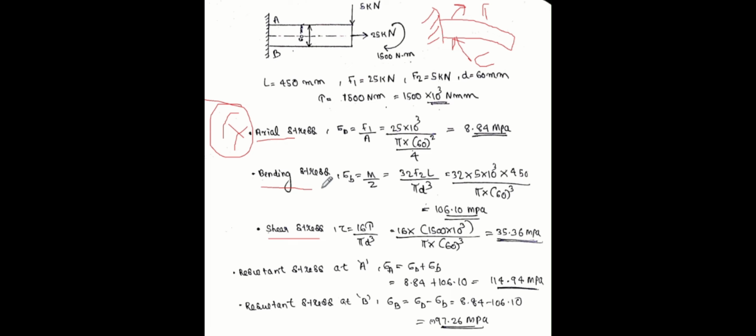Next, they simply ask to find the maximum stress at points A and B. In these cases we have to find the principal stresses. Okay, this is that type of question. So, the principal stress at A. Let's just consider the top portion alone.